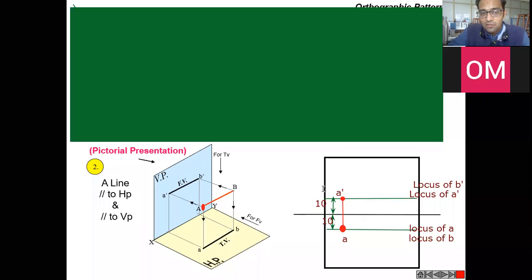So now we have to consider true length of line, which is 50 mm. So we are going to draft a line over here. This is going to be the 50 mm, and at the end of 50 mm, we are going to place another point, which is going to be called B dash, and we will transfer projection of B dash from this position to the locus of B, and now this is going to be the position of B, which is plan of B.